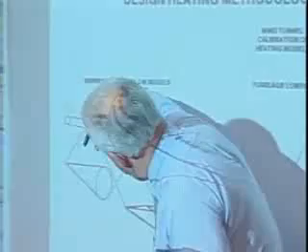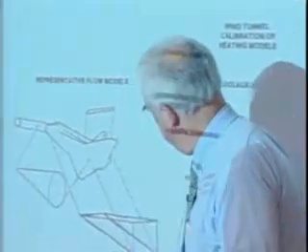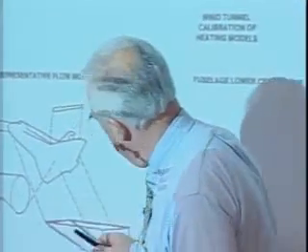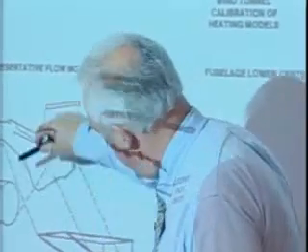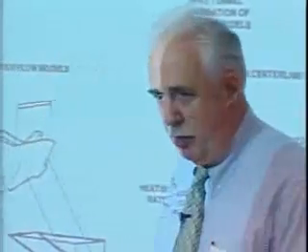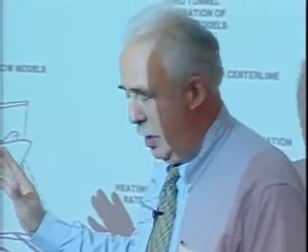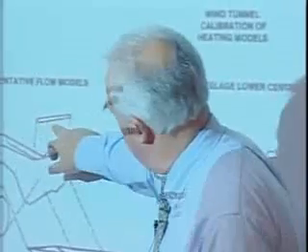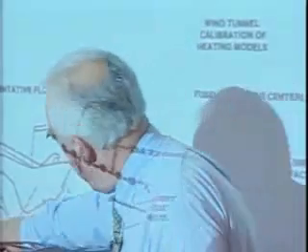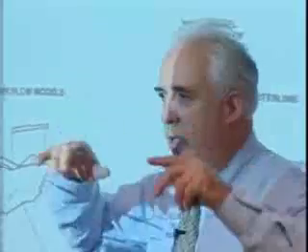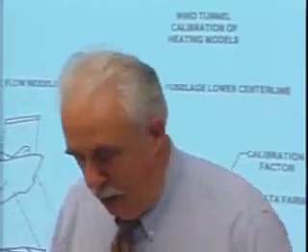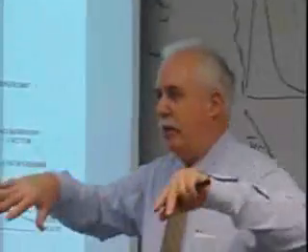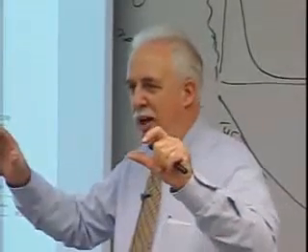I look at flow down the center line, and I'm sorry, this wedge didn't show. This is supposed to be a wedge or flat plate at angle of attack. This flat surface down here looks kind of like a wedge. Well, I can calculate a boundary layer on a wedge, given the pressure, which Newtonian would work fine, certainly in the blunt regions, and on a wedge I can do that flow. I can do a swept cylinder for the leading edge, and I can do a cone for where the boundary layer spreads. I take diagnostics in the wind tunnel, look at the boundary layer path, say, boy, this thing is spreading kind of like a cone.